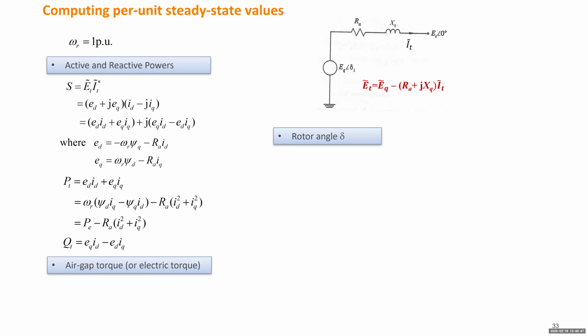Also, we know the imaginary part of the complex power will be QT, which is the reactive power. If you took my 421, I actually explained that the power is the inner product of the voltage and current vectors, because this expression is the definition of the inner product. And QT is the vector product of the voltage and current vectors.